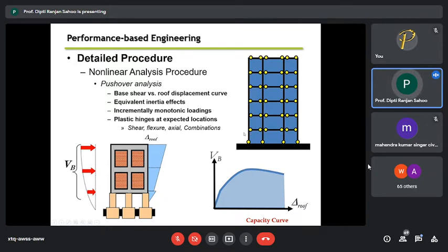So in a sense, you apply maximum displacement here, or you apply a profile with maximum roof displacement 10 mm, corresponding to, let's say, this, and then you increase 10 to 15, keeping the same profile. That profile may be consistent with your lateral force distribution, or consistent with your mode shape. It can be anything, but it has to be consistent with your structural performance or loading condition. When I say the mode shape, it is the structural performance. When I say the loading condition, probably your lateral force distribution over the height of the structure.